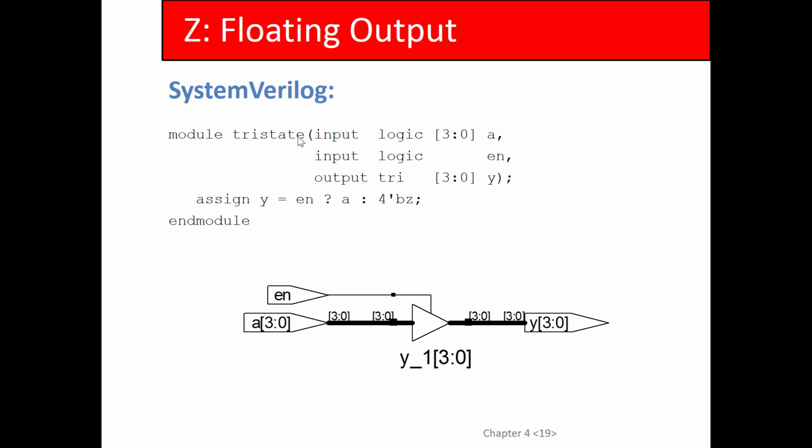Now the question is synthesis tools: how to convert that to hardware? I have never found an open source synthesis tool. If you find one, let me know. But that is a bridge too far for open source. Actually doing this to this, doing exactly what's on the slide, taking this and generating that, there's no open source that I know of that can do it. There's a website called EDA Playground that provides a cloud-based version to do simulation and synthesis. But it turns out that under the hood, they're just using the commercial tools.